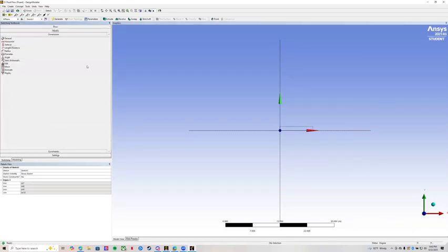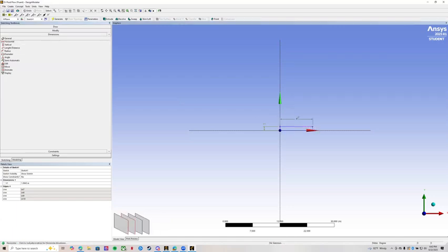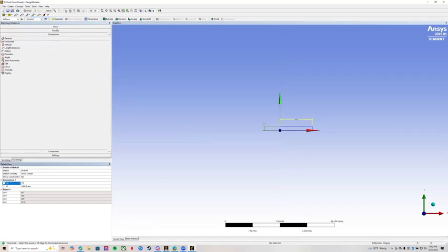Go to dimensions. Select vertical and horizontal because we're going to change those dimensions to what we need. Make sure they're the correct length for what we calculate our Reynolds number and everything else for. So first things first, go ahead and change your units to millimeter. That way we're working in the correct units. So our horizontal, we're going to do 1500 because we're going to do a height of 10 millimeters. This way, following that condition we were given, which was the 150 times height for our length, we can go ahead and select those dimension parts and delete them. The dimensions are already done, but this way we don't have those being in the way.